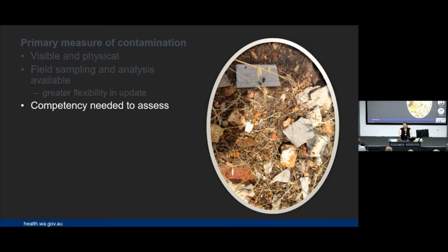If you're fairly assured that it's fairly intact, broken pieces, then you probably don't need to. And a decade of sampling has shown us that you rarely find AF even close to 10% of the bonded material in the soil. So not even close to that. That's why we took that approach, it's going to be less than 10% the AF, because often it's even less than that. We've rarely even found 10% of asbestos fine material related with bonded material.